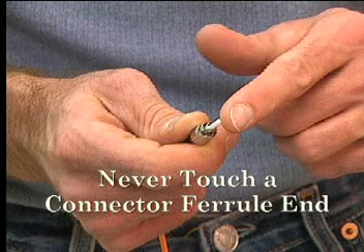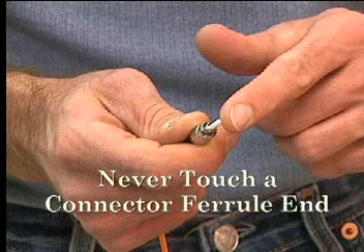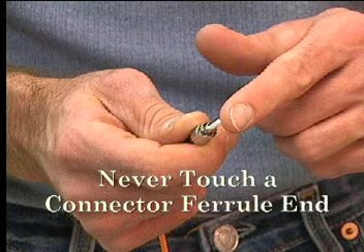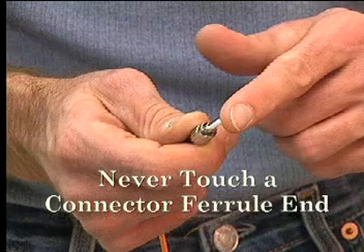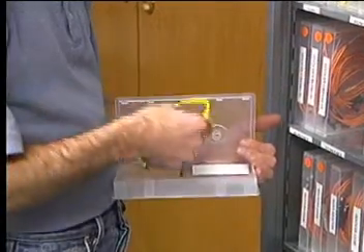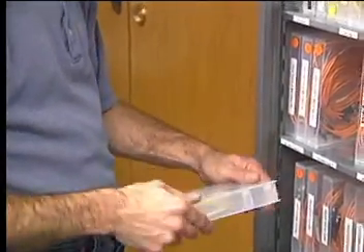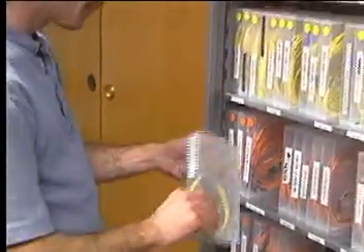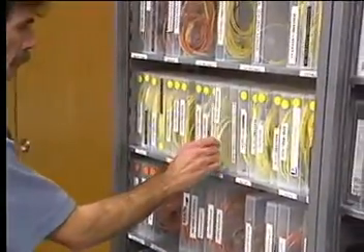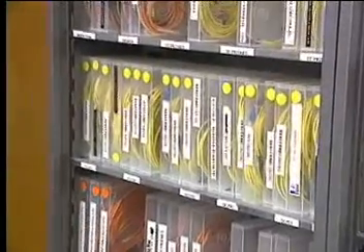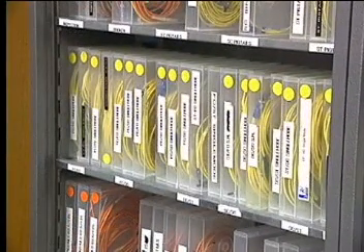Never touch a connector ferrule with your fingers. An astonishing amount of skin oil will adhere to the ferrule from even the cleanest hands. Store unused jumpers with connectors capped in Ziploc plastic bags and place them in boxes or other containers where heavy articles will not come in contact with them. Plastic video cassette boxes are a convenient option.